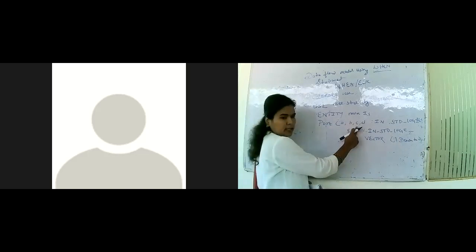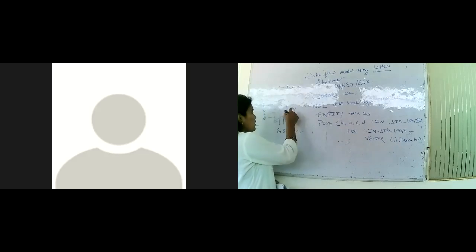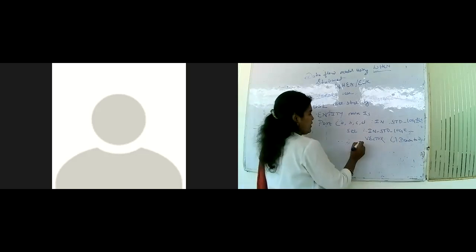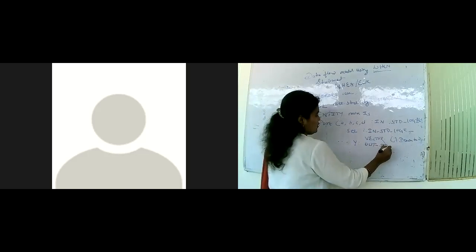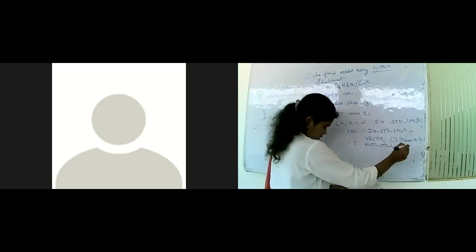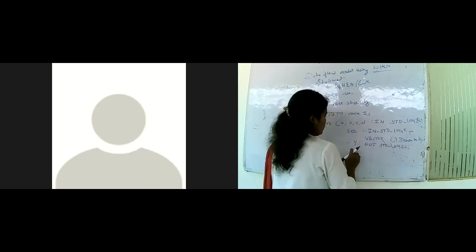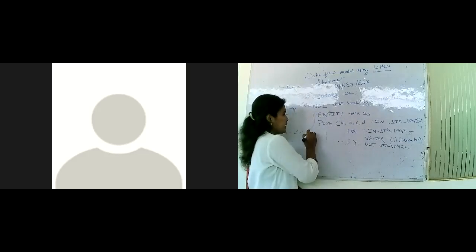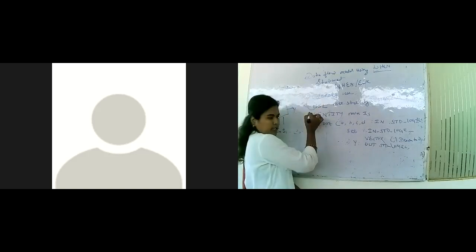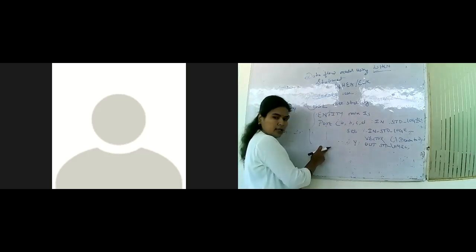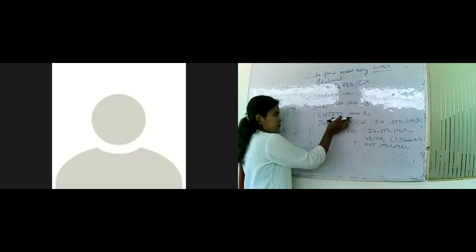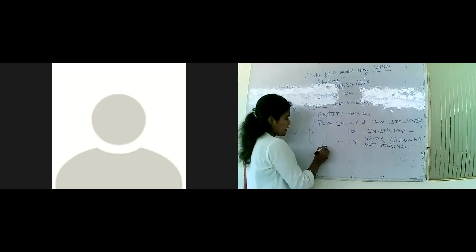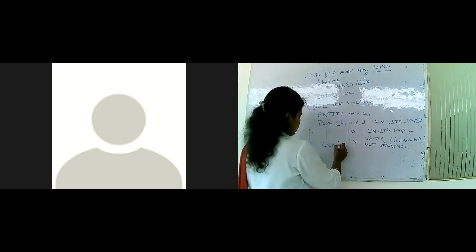Next one is output. So it is input, it is selection line, and next one is output. For the multiplexer, there is only one output. Out, std_logic. So this is the entity, the entity portion. In the entity, we are just telling which are the inputs and which are the outputs. When we start the entity, we have to end the entity here. End of multiplexer.